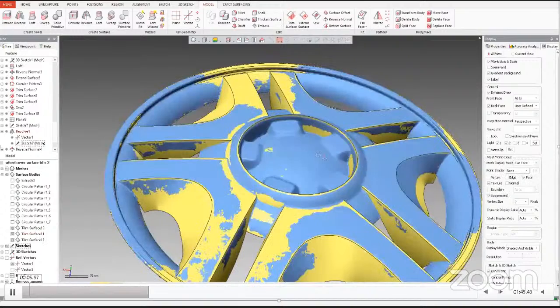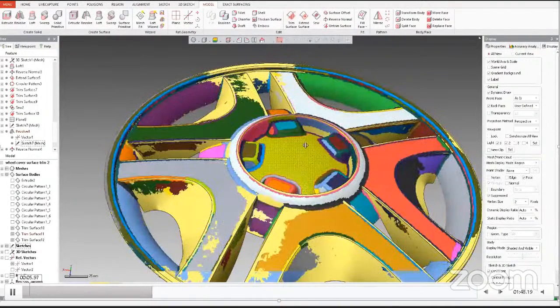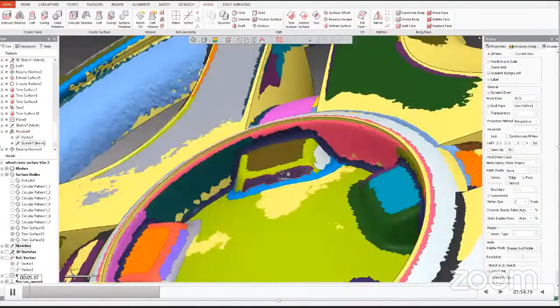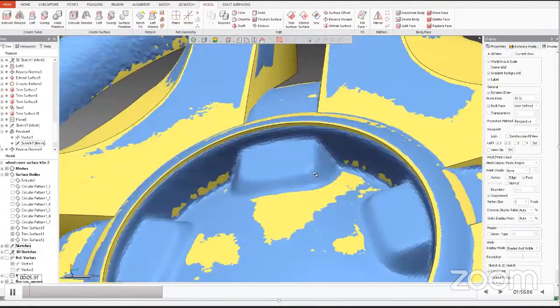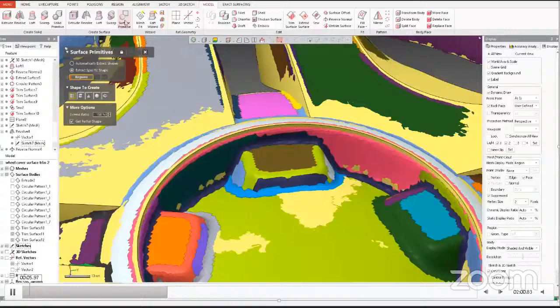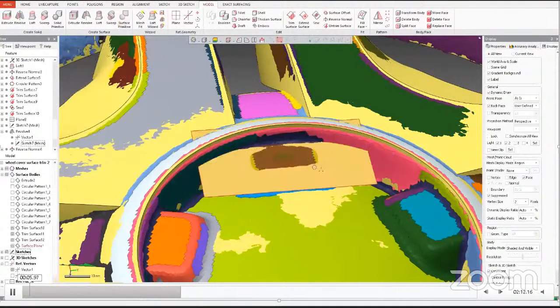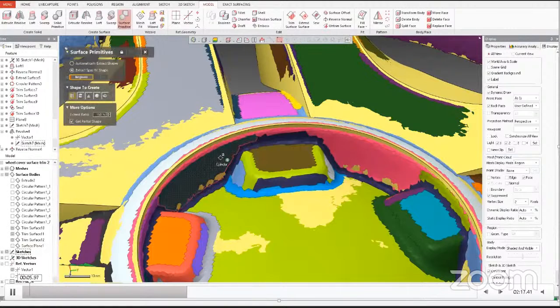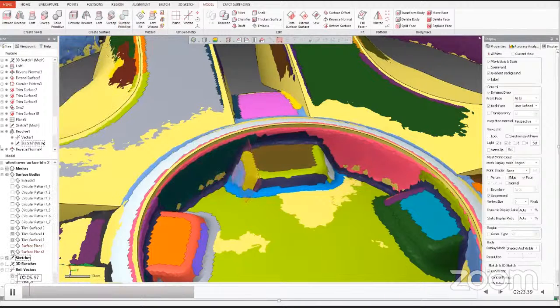So now the only things left are these boxes that we have to create, and then apply some fillets at the corners or at the edges. We can create these types of boxes with the help of surface primitive. We go to surface primitive, extract the specific shape, and then extend the ratio. Like if we extend the length and height of it, it just creates the plane surface. We try to extract the plane surface once again on the sides and do the same procedure for the front and for the right side.